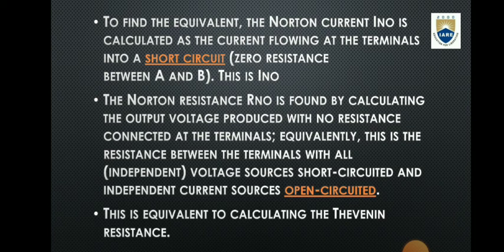Equivalently, this is the resistance between the terminals with all independent voltage sources short circuited and independent current sources open circuited. This is equivalent to calculating the Thevenin's resistance.